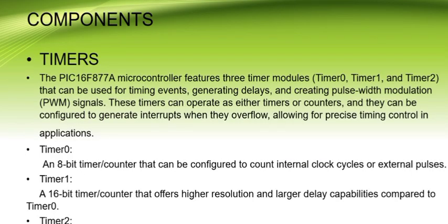Timers. Timers are essential in embedded systems for scheduling events. PIC16F877A has 3 timers. We used them for creating time delays between washing phases and for PWM signal generation when required.